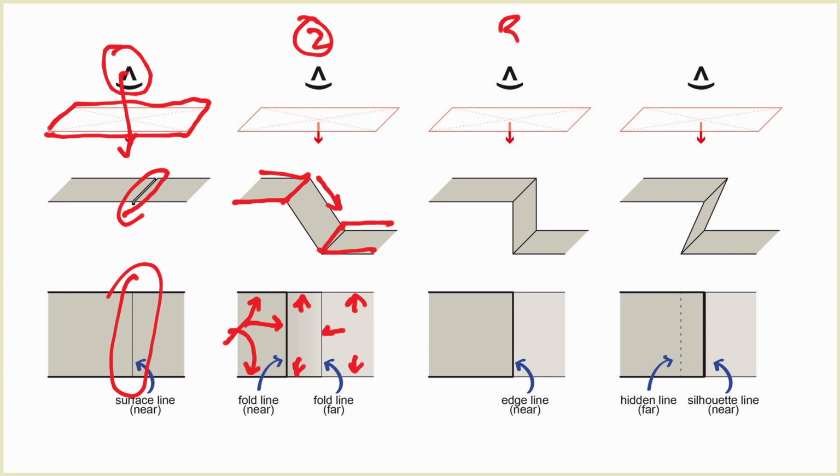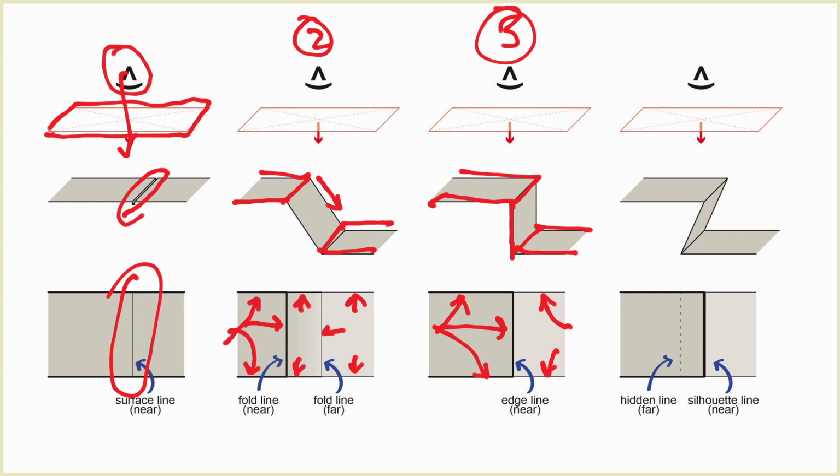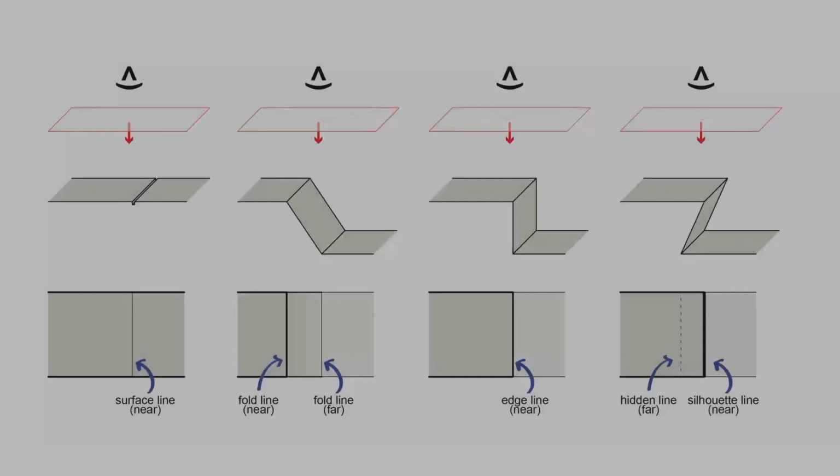When we move to the third example, number 3 here, that's a terrible 3, but you get the idea. In this scenario, we have one plane that's up here, straight drop to the second plane that's down below. In that case, the thickest lines are right there. Again, the piece that's closest to us, and the thinnest lines are down below. In this last scenario, number 4, the plane tucks underneath itself right there. And in that scenario, we're getting a different line type. We're getting that dashed line. Same in terms of thickness. What's on top is nice and bold. What's down below is nice and thin. But the dashed line is referencing the fact that the bottom folds underneath, as opposed to being inline or outbound from the upper plane.